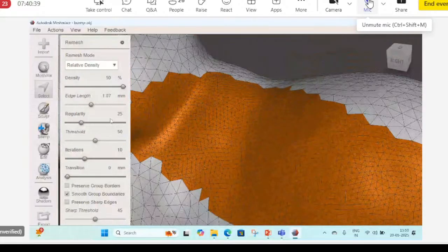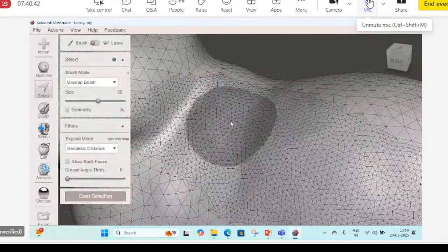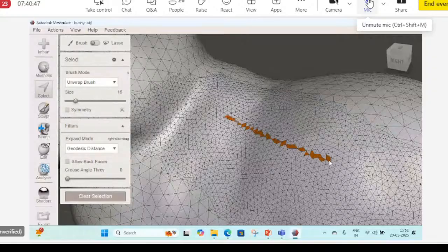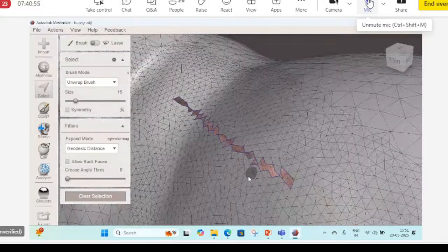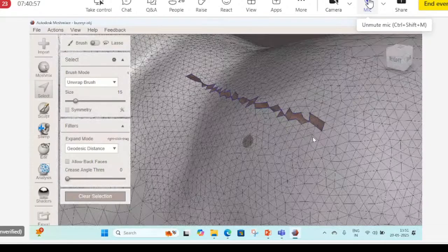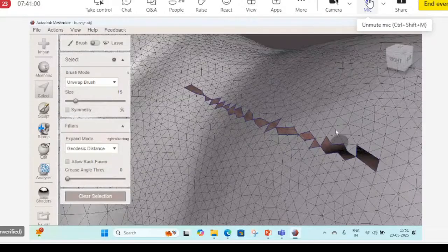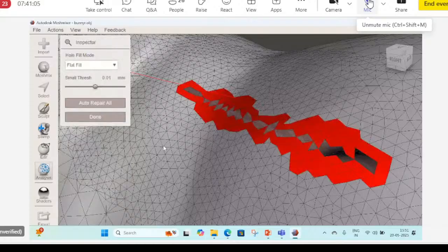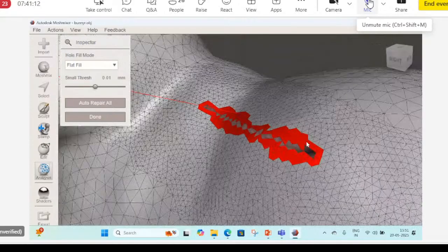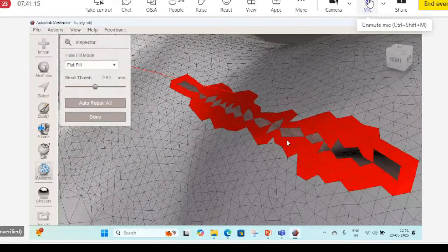And one more thing that I want to show you. Suppose I have deliberately deleted these triangles. Now the STL has an error. It has been punctured deliberately. Okay. If you want to check for holes, you can analyze your STL file with the Inspector command, and it will give you the reason immediately. This is where we have a hole. If a hole persists, we can fill it.